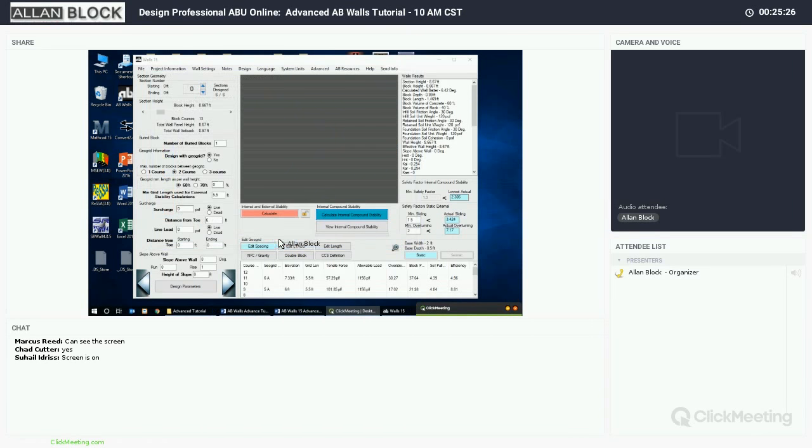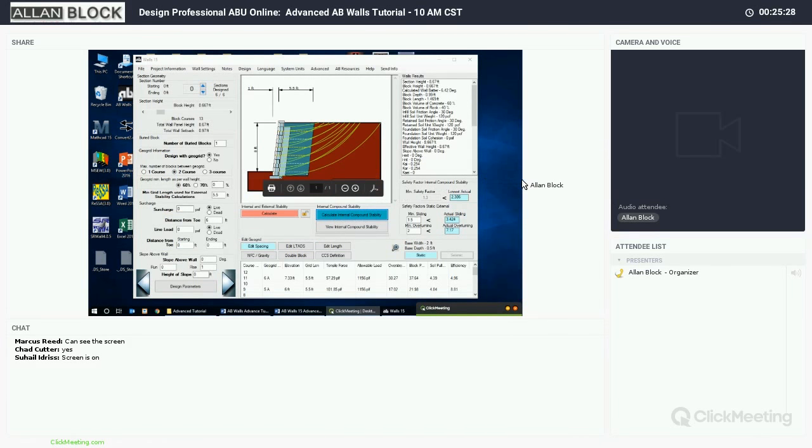So if I hide this, what you're seeing is the lowest safety factor slip arc for each course. Remember I said that first arc is not touching that layer of geogrid, so that's why you had zero contribution for that resistance. But everything's green, so we're in really good shape. No problems whatsoever. But maybe, again, a site condition, maybe we have that 3-to-1 slope above the wall. So I've got that 3-to-1 slope.